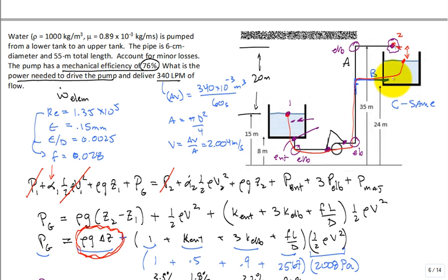I'd now have a submerged loss coefficient, which is the same as throwing it out with kinetic energy at the top. So those would be the same. I'd have the same 90-degree turn. I'd have the same length going horizontal, but slightly lower length because I wouldn't have to lift it as far. So the major loss would go down a little, but where would be the biggest change?